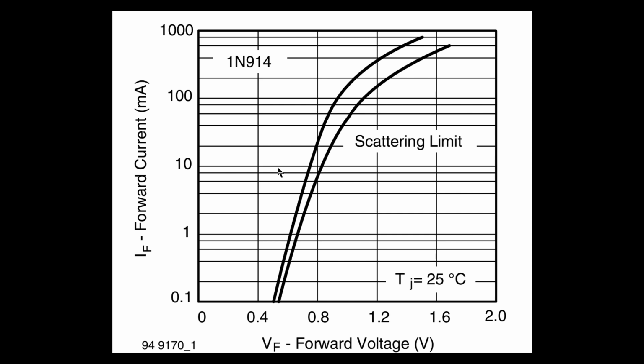What we need is to be able to supply a fixed amount of current to a diode, no matter what its voltage is. Now think, Ohm's law kicks in. If the voltage is varying in most circuits, that would change the current. Because of that, we can't just put a resistor to limit current and feed to a diode, because each diode would vary and make the current go up and down, and you wouldn't get an accurate reading.